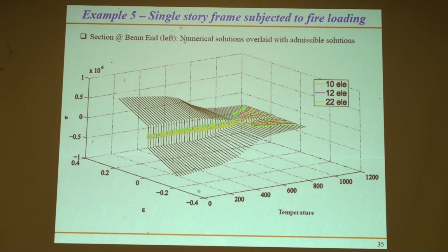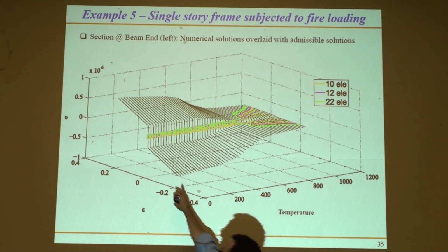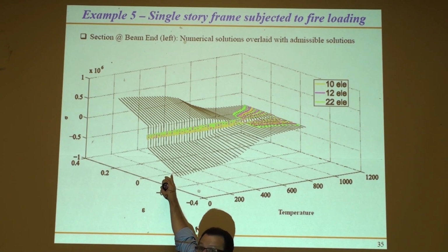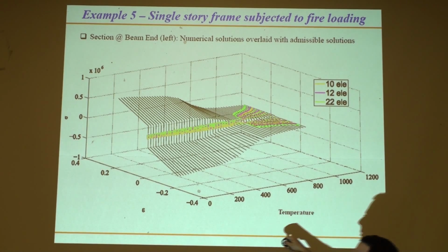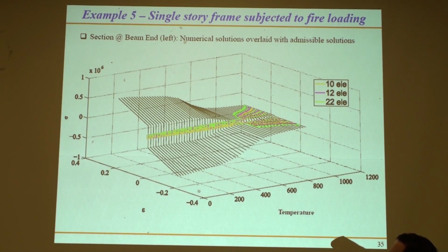I really like this plot, especially because I've been looking at OpenSees for a long time just as an earthquake engineer. So I would be looking, let's say, at a temperature of 0 or 20 degrees Celsius, and this would be the response that you would see, or one of these lines would be the response that you would get for Steel01. The stress-strain response that you'd see for Steel01: an initial elastic branch, and then a branch which is b times your initial stiffness, with the hardening, right?